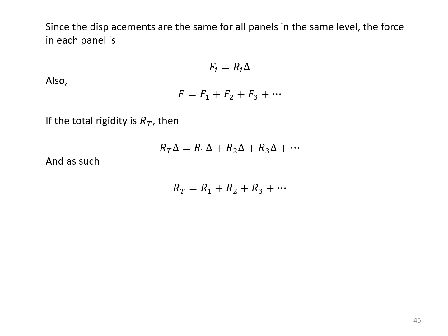All right. Now, therefore, for each panel, if I take the rigidity multiplied by delta, I get the force. And remember that F1, F2, F3, etc. add up to F, which is equal to 1, right? So now I'm going to substitute for each of these F's.